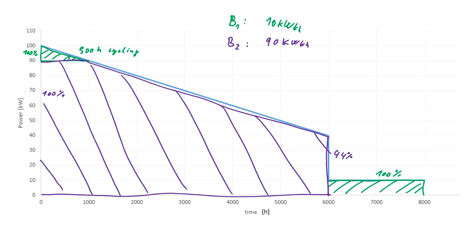So even though the limit is 20% of the power output, this 2 kilowatts would be definitely covered by the capacity of the distribution system, the piping itself, and during the transfer regimes, and by the cycling of the boiler.